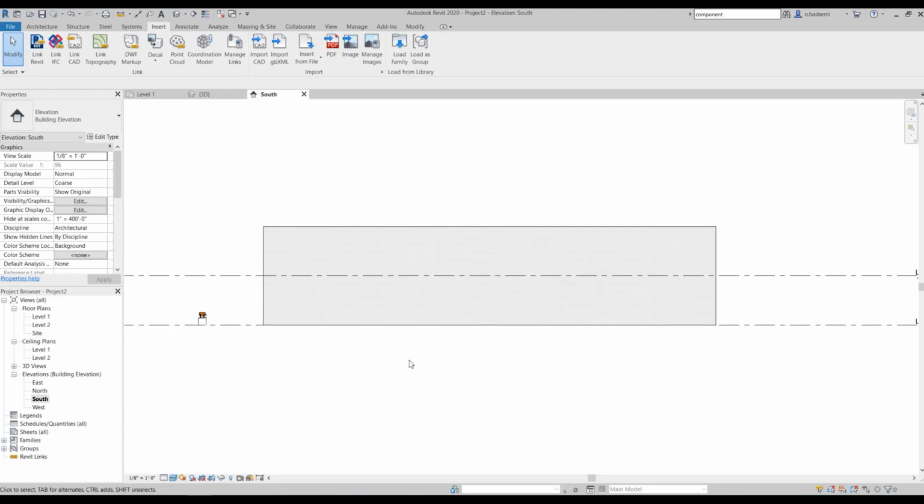It will not allow us to, for example, calculate cost or the amount of brick we need. So painting is good for appearances, but it's not a good method to use if you need to, for example, calculate a material or how absorptive the wall is. So adding material with paint, which is actually by face, adds no information to your model. It just changes the appearance of your model. Now let's see how we can do that.